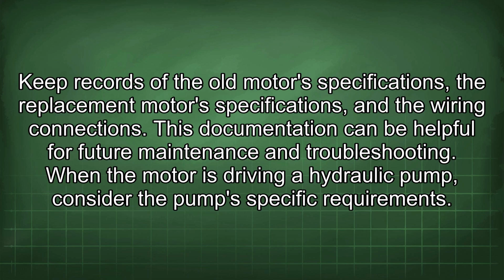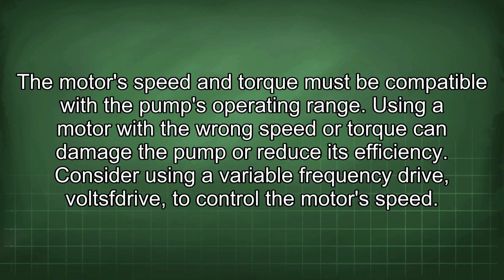When the motor is driving a hydraulic pump, consider the pump's specific requirements. The motor's speed and torque must be compatible with the pump's operating range. Using a motor with the wrong speed or torque can damage the pump or reduce its efficiency.